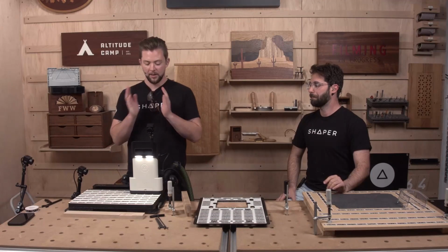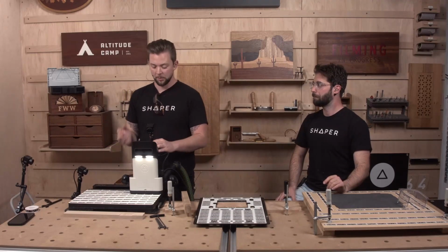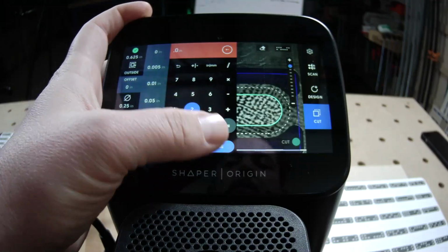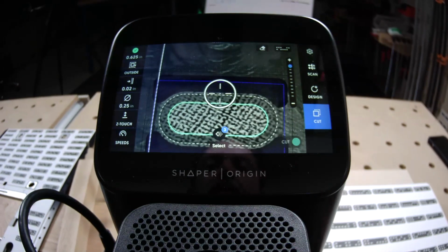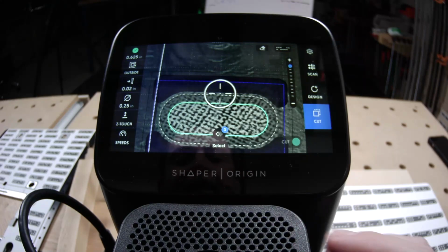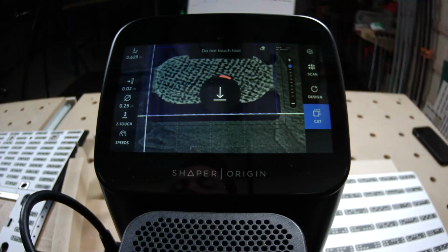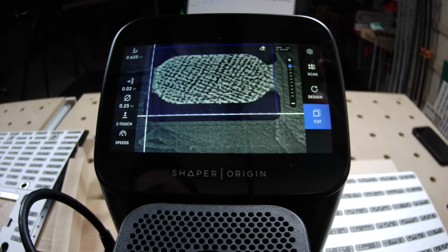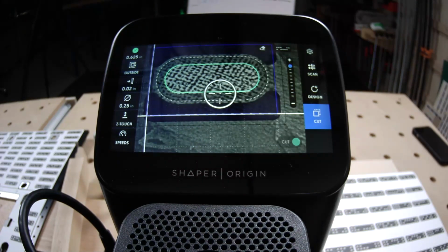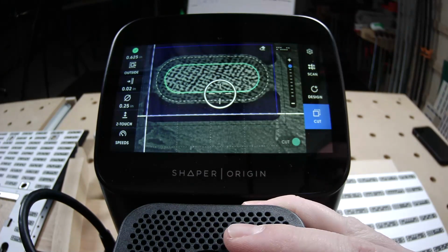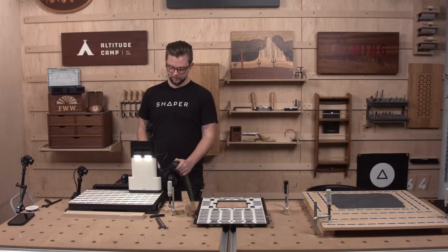All right. So I'm going to go ahead and cut these. A couple of passes. Do a rough offset. Yeah, you're going to go straight to 0.625? Yep. All right, awesome. Help me keep track of the cuts over here. Got to make sure I automatically Z-touch off the top of my tenon. Right, always double check your Z-touch. Yeah, get that dust guard. I'm going to step off to the side over here so that the noise from the router doesn't drown out my microphone, so that I can narrate a little bit as Jake cuts.